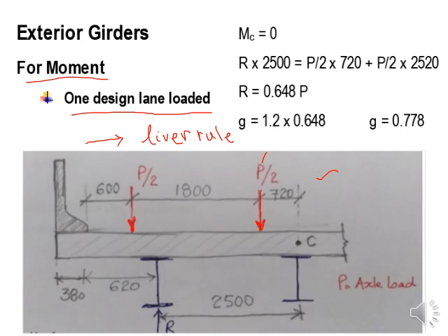Okay, in this particular direction, half will come in the third direction. In this lateral direction, one wheel has been placed and the second wheel will be on the other side. So half the load is coming on this side and half the load on the other side. So P by 2 needs to be considered for your exterior girder.